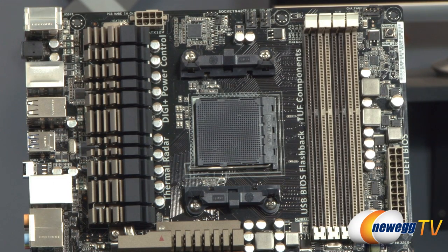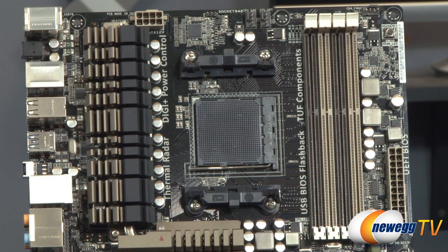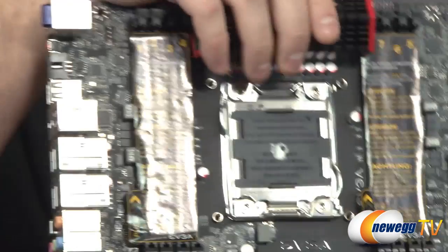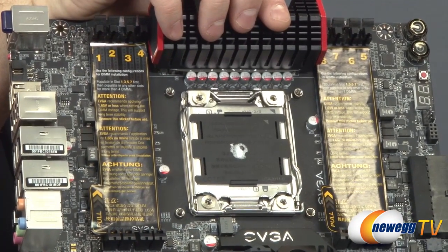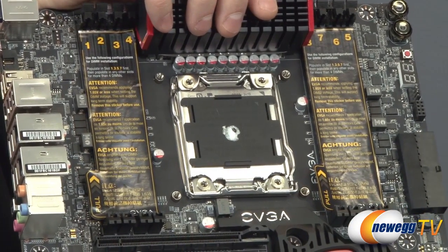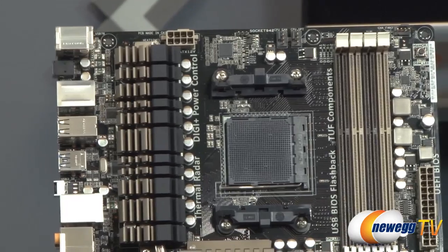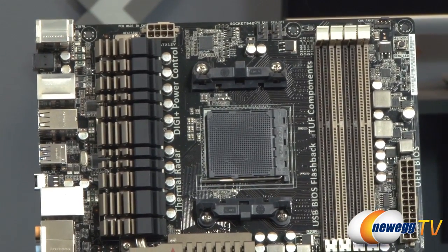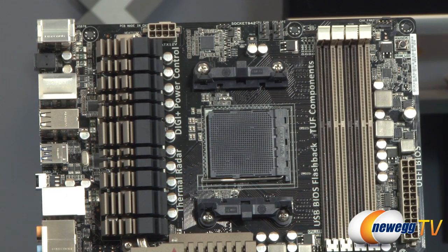Memory slots? Memory slots are usually also located adjacent to the CPU socket, so on here they're just to the right. For an Intel board, for example, like this one, they actually have it set up so you have 2 sets of banks, 4 on either side of the CPU. Typically, all motherboards right now have DDR3 memory. We might see DDR4 start to be introduced next year. Just make sure that you get a dual channel kit or a quad channel kit as necessary depending on the platform that you're running on, and DDR3, and then choose whatever speed you're willing to pay for and that is compatible with your chosen CPU.